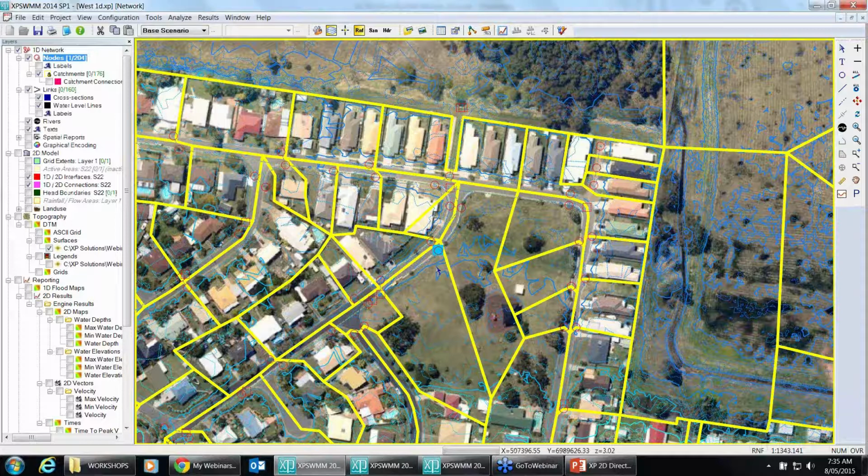And you could apply the EPA runoff method or other method as required for your local area to generate a hydrograph. And that hydrograph would not show any surface flows in the upper component of that catchment. The flow starts at that point. And that's the core difference that I see between traditional methods to the direct rainfall method.